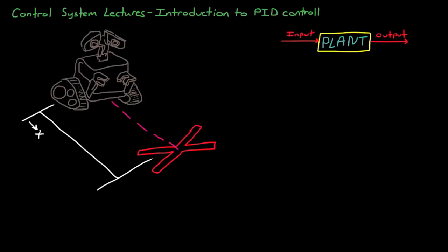And open loop commanding is perfectly fine for systems that don't change much or where accuracy isn't as important. However, what if there's some dirt in one of the wheels and the robot veers off to the side? Or if the robot's slightly faster than you had predicted? In both of these cases, the robot won't stop on the red X because it has no way of compensating for these errors and making adjustments on its own.